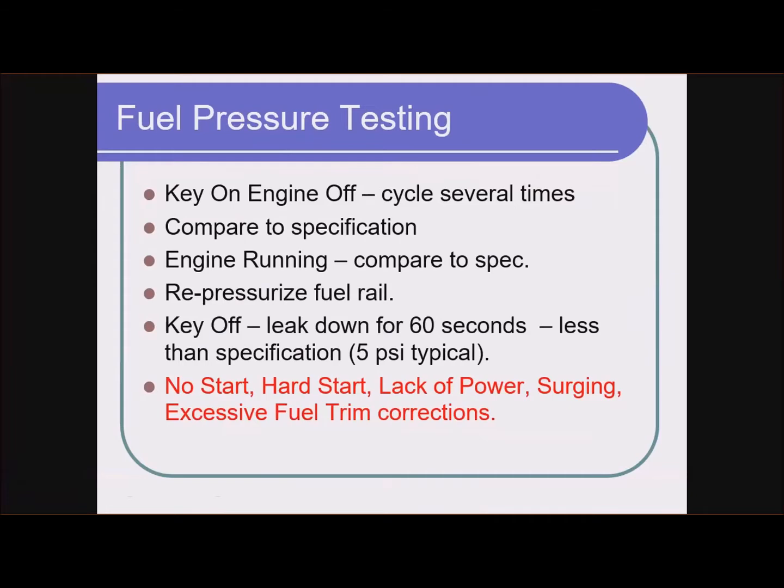Keep in mind, if we have a gasoline direct injected engine, then there's really 2 fuel pressures. There's the electric pump in the tank. Some people call it a lift pump. This just supplies fuel to the high pressure pump that's going to be up on the engine, probably driven off the camshaft. So you're not really seeing what pressure is available to the injectors on a gasoline direct inject engine.